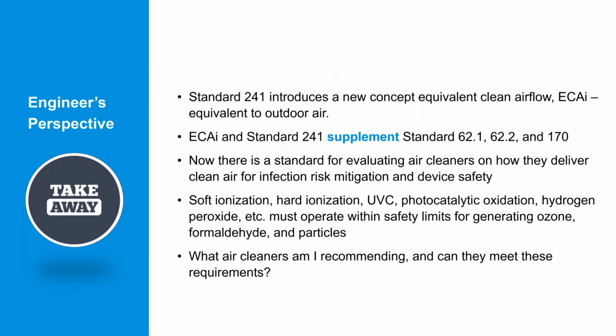So let's pause. I know I introduced a handful of different concepts here. This new standard or new concept of equivalent clean airflow, known as ECAi, I think will be very helpful. It's for CFM per person. It is a supplement, so 241 supplements 62.1, 62.2, and 170. It does not replace them. In fact, 62.1, 62.2, and 170 are the prerequisite for 241. There's now a standard for evaluating the air cleaners and how they deliver clean airflow for risk mitigation and for device safety, which is very important.